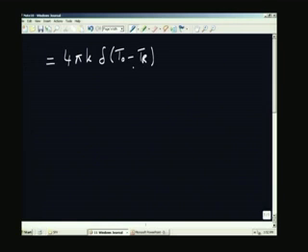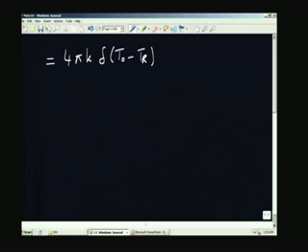Of course, T naught is already a function of time. Instantaneously there is some temperature. The assumption I am making is that at any instant of time the temperature comes to a local steady state value and goes from one steady state to another steady state locally. That means that the shape of the curve is not changing, and under that condition you are going to get this one. So, now I can write the final equation.